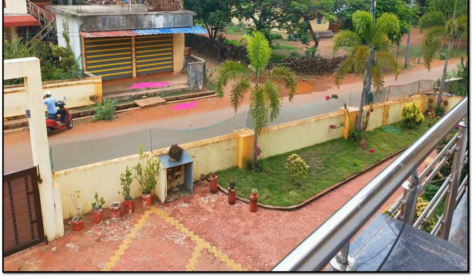So whenever you transfer the level, the road also will have a certain level that you get from the road department, like I mentioned in one of my lectures, on how you have to transfer the permanent benchmark. One you get at the railway station, second you get from the inspection bungalows, or if you go to the road department, the road will have a certain level. Based on that, from this road level I'll construct my FFL 1 meter above that or 2 meters above that. In that way we try to decide it, right? Yeah, so this is the basic understanding of that.